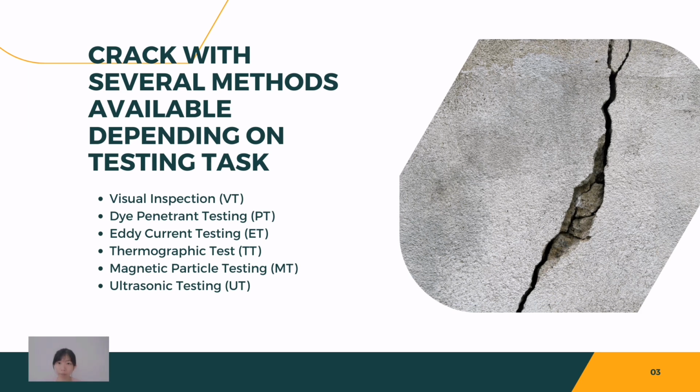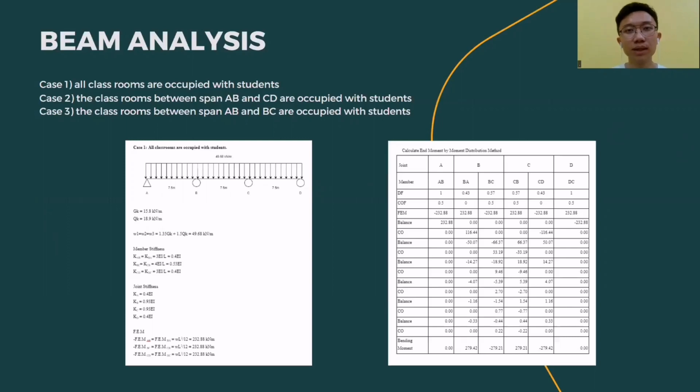Then, the magnetic particle testing is the earliest technique for identifying material defects. This technique involves magnetizing and misting magnetic powder onto ferromagnetic components. Different test part flaws respond to the magnetization in different ways. The magnetic field is now more prominently seen on the surface. The magnetic powder can have a fluorescent material added to it to make the flaws glow in different ways depending on the illumination. Next, we will talk about the beam analysis.